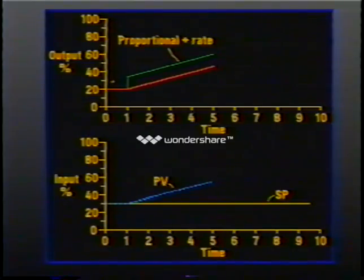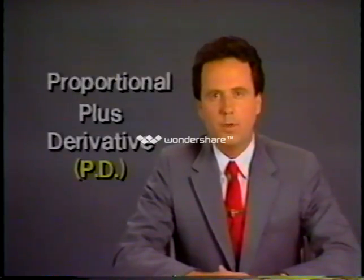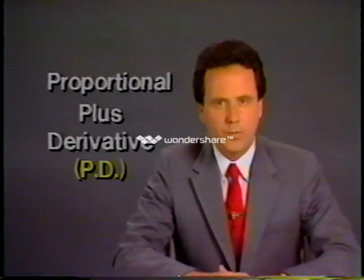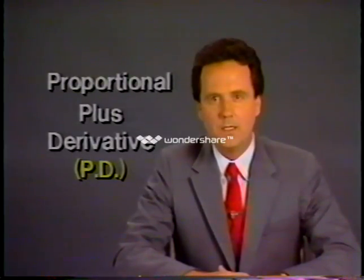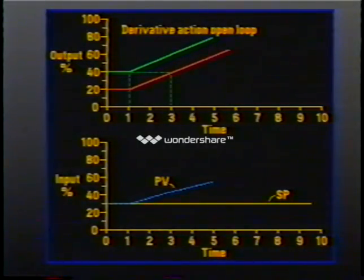The rate action mode makes a change in the controller output equal to this value, and it does so very quickly as soon as the slope of the change can be detected. In a proportional plus derivative controller action, the total controller output is the effect of rate plus proportional gain. Of course, if we had a higher gain setting, the slope of the proportional curve would be steeper, which would make the rate output larger as well.